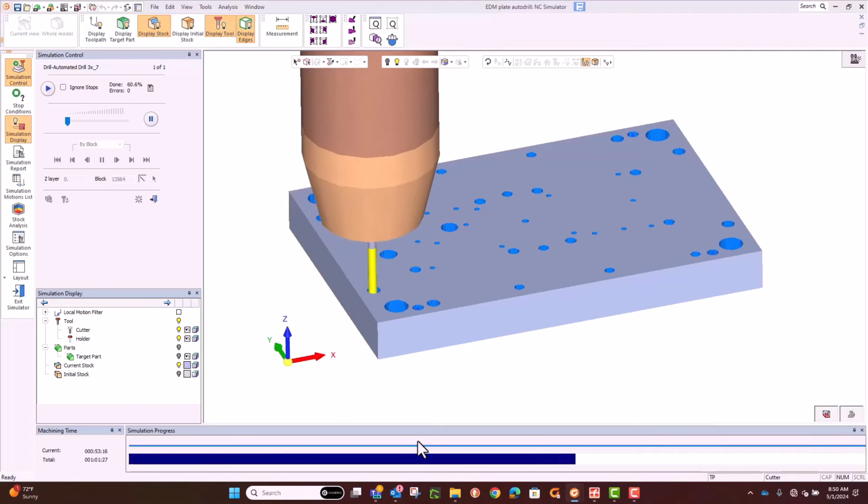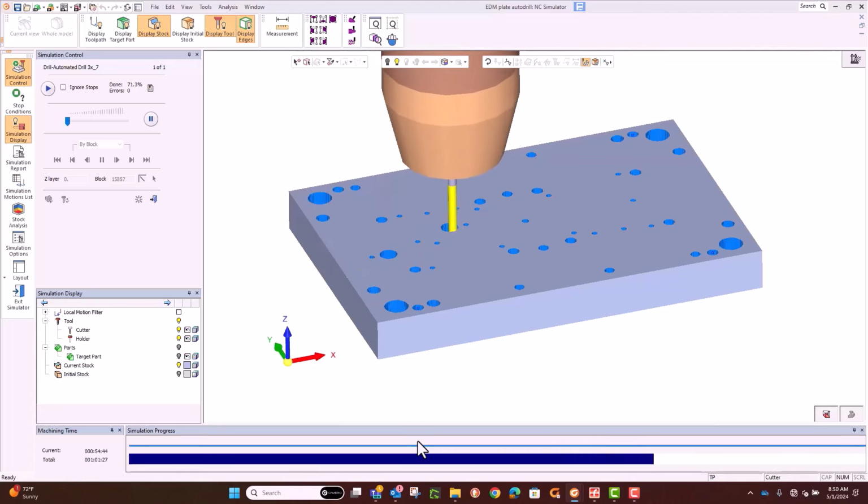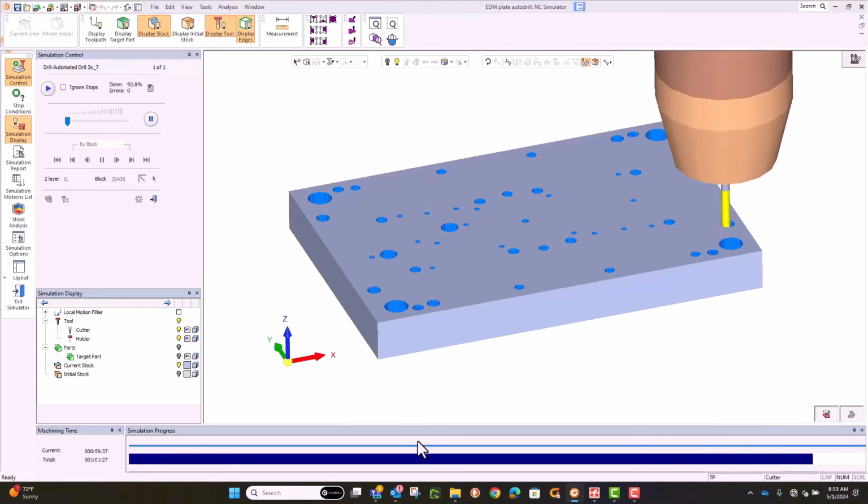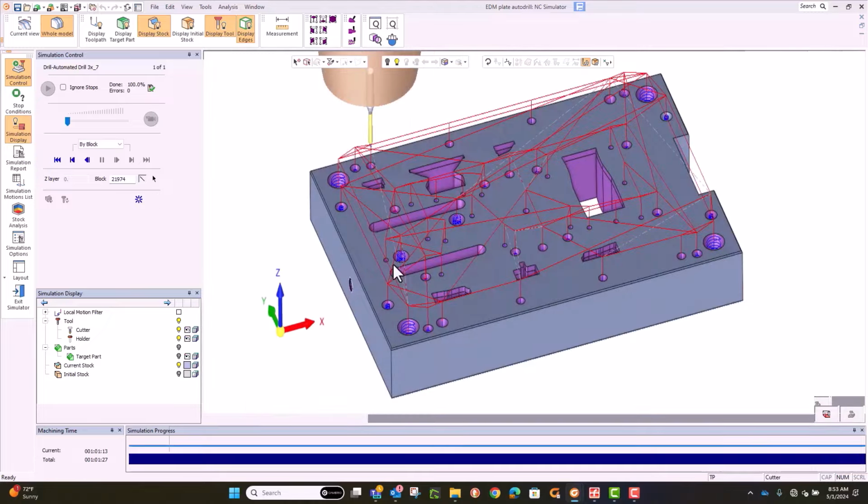So if I have like a drill hole, like a 201 hole, that's going to be a clearance hole for a quarter 20 tap, or I'm sorry, a drill hole for a quarter 20 tap, but it can use that 201 somewhere else. It'll do all the 201 holes, then come back and do the next drill. So it's a smart way of doing the automatic drilling.